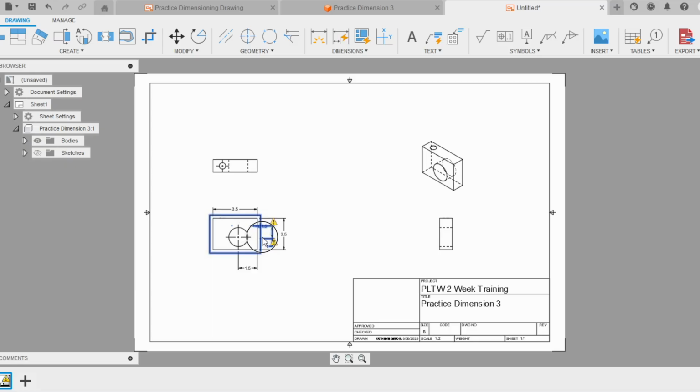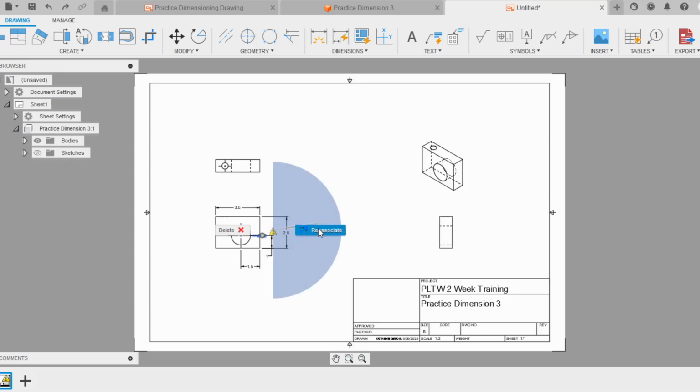But anyways, you see me get the diameter, and I want to make that diameter symbol clear, because if someone else were to read it, they would have to see that it says diameter. So I get it to a spot where I want it to be clear. And I do the same exact thing basically for the top part of the drawing, because that top part of the drawing has the same situation where there's a circle, and you have to mark where the center is, and then the diameter, because the diameter of a circle does run through its center, which is why it's really important in dimensioning to mark where the center of a circle is and the diameter so you can see how long it is.